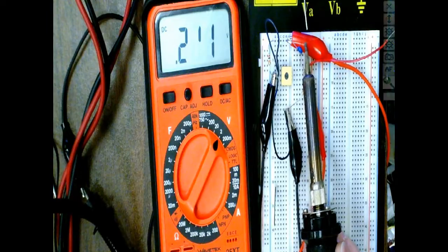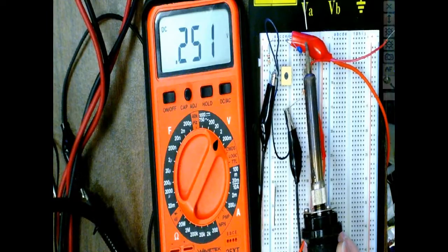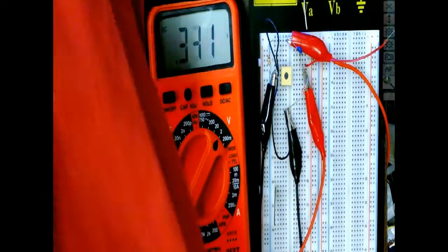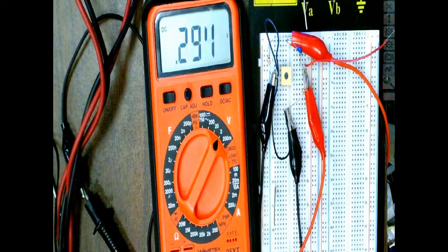So we use this a lot for, I'm not going to say any, most transducers that vary their resistance with what it checks or what it measures use a Wheatstone bridge. Why? Because that way we can come up and we can set what 0 is. What's our origin? Where are we starting measuring this temperature from?